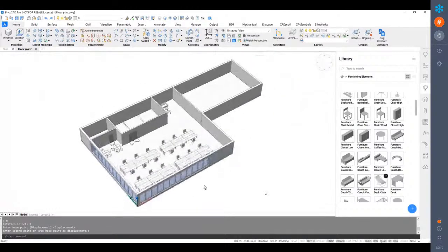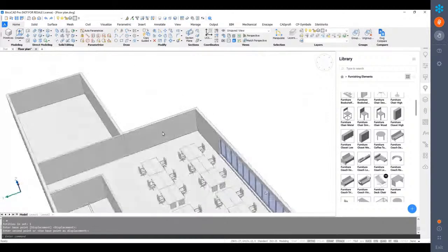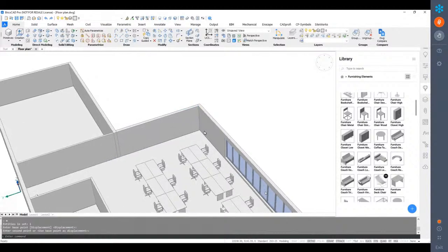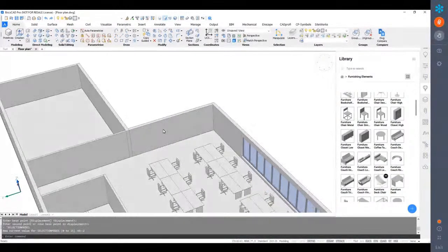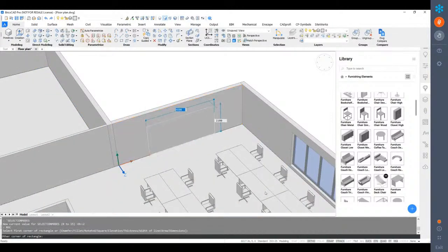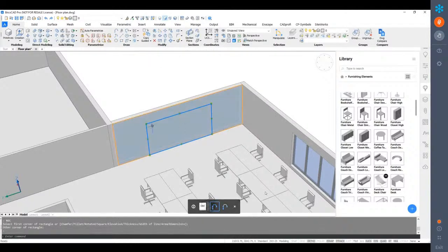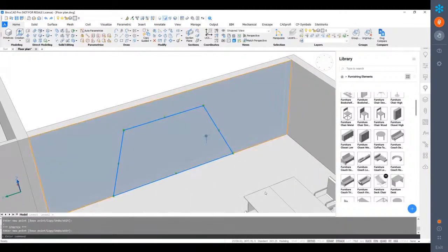Okay. So yeah, as I was saying, let's say you have something more customized in mind, and maybe you want to have a bit more of a special shelf on this area because it's a huge blank wall here. So with BricsCAD, I can also make sure that I am just focusing on one of the faces, and I can use the usual rectangle perhaps to just start off my shelf here. Nothing fancy, just a rectangle. So this rectangle now I can manipulate by just shifting these grips. Actually, I think you'd be quite used to this.